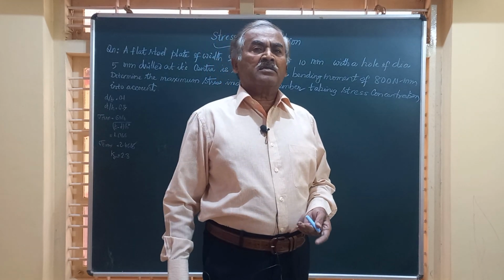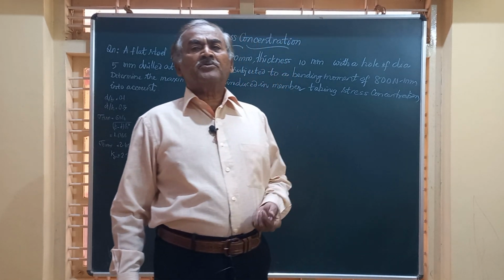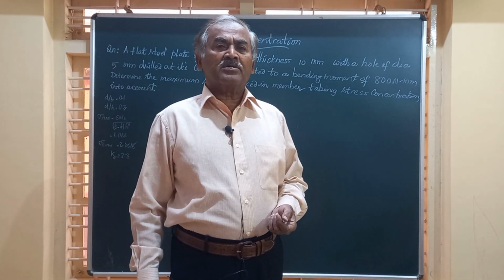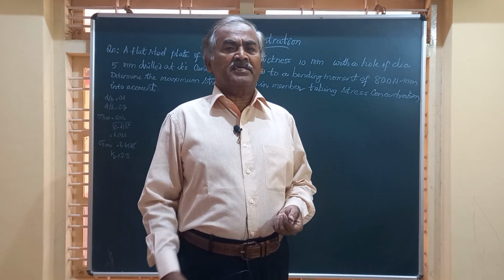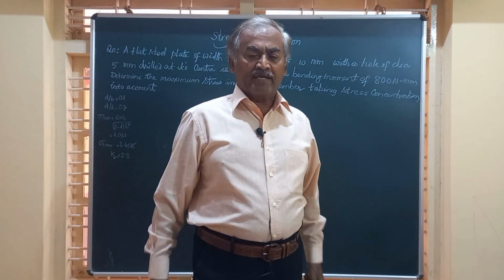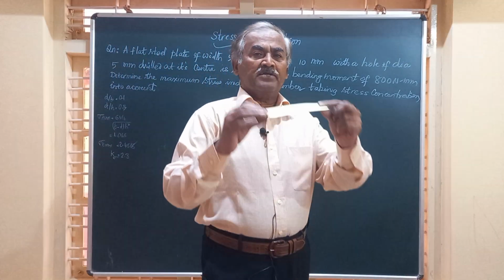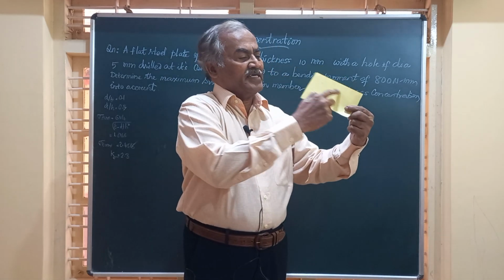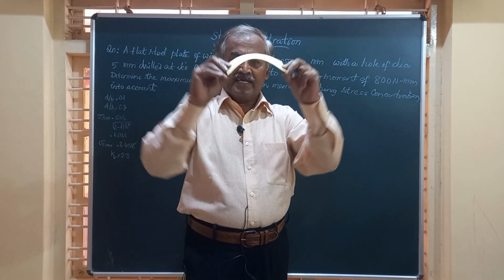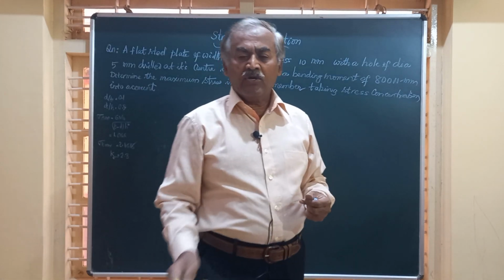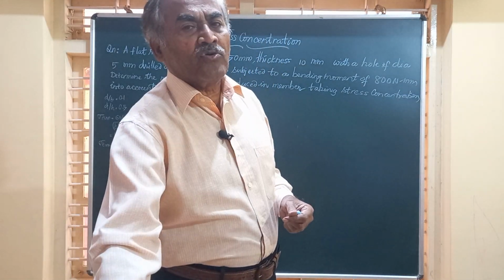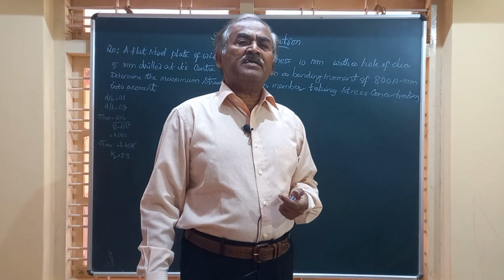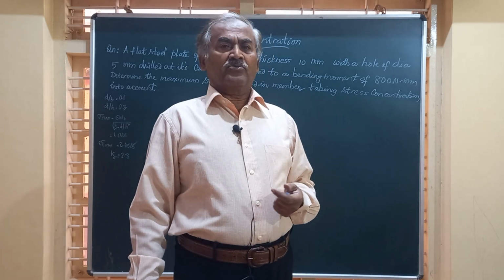In today's video, we are going to work out a problem on a steel plate having a hole drilled at its center and subjected to a bending moment. The steel plate has some thickness and width, and a hole drilled at its center, and it is subjected to a bending moment of a given value. We are going to find out the maximum stress induced in the member, taking stress concentration into account.